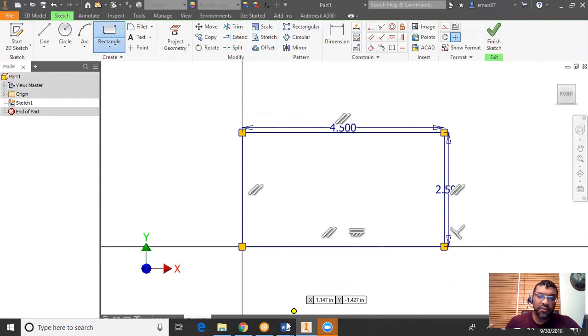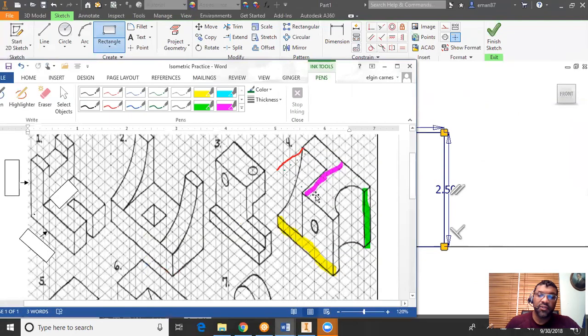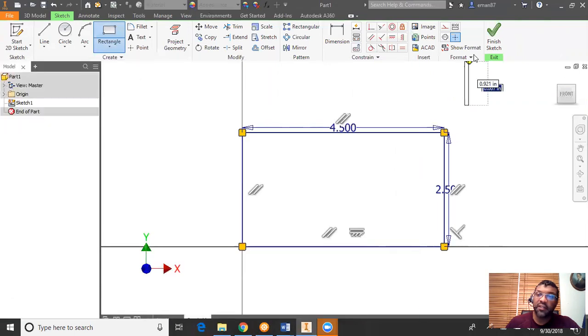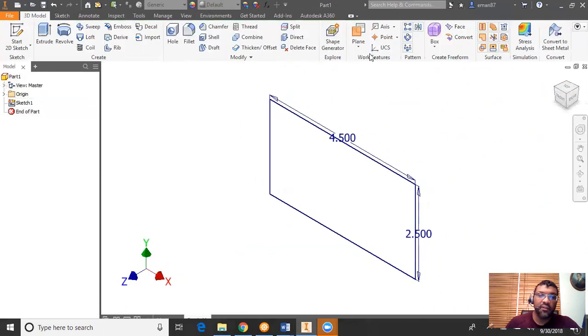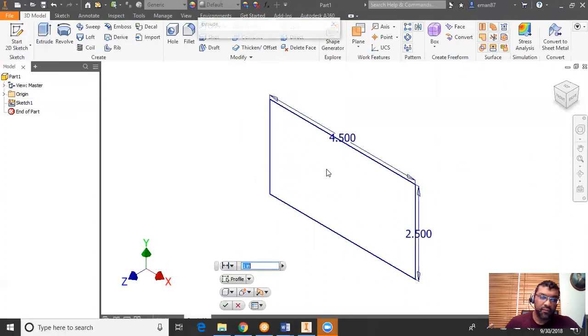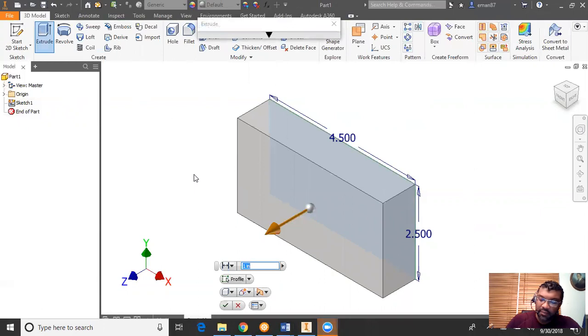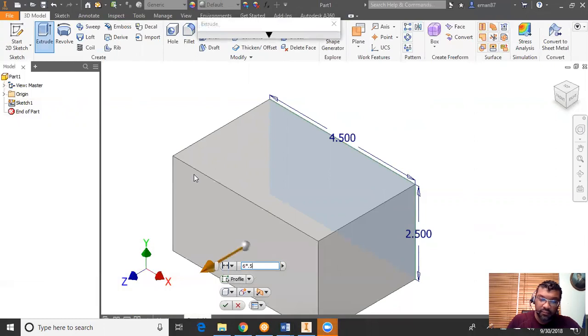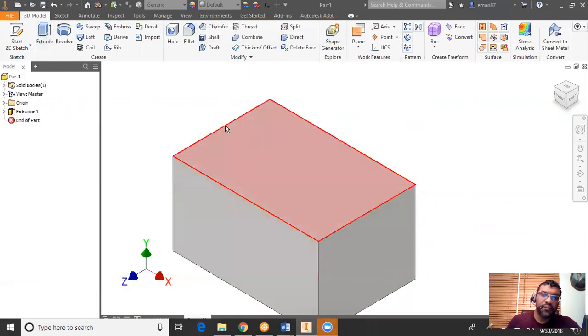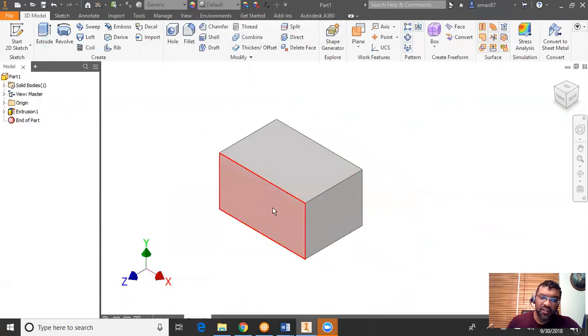So remember the extrusion. Let's go back here and check that. The extrusion here was this purple line, which is 6 boxes long. So it'd be 6 times 0.5. So I'll do a finish sketch. Zoom back into view. Go to extrude. And I'll type in 6 times 0.5. Now look at this as like a big piece of clay, and we're going to carve in all the features here. So we need to go back and analyze the drawing a little bit.